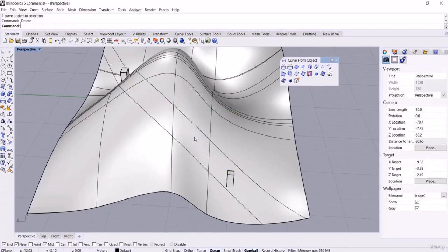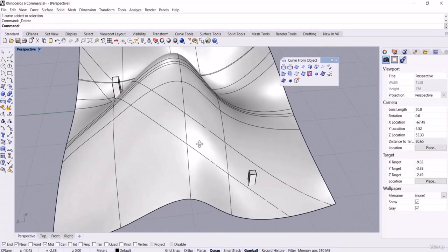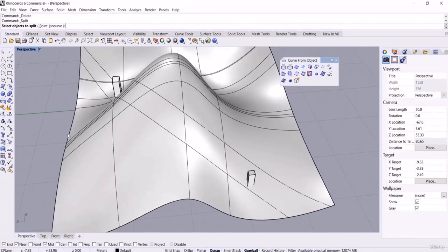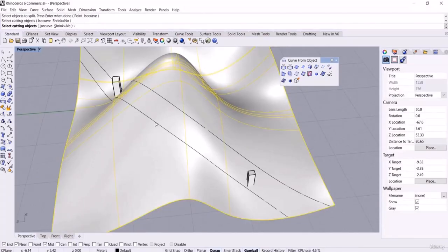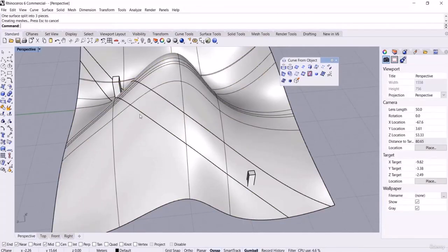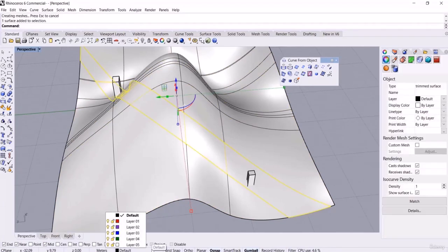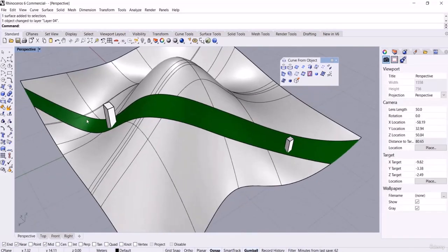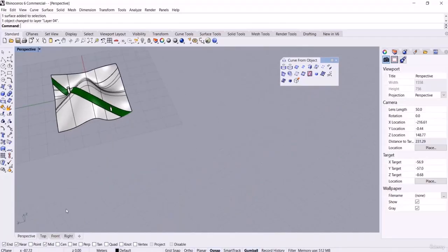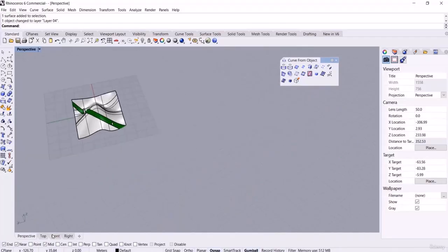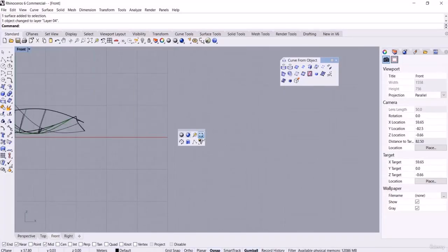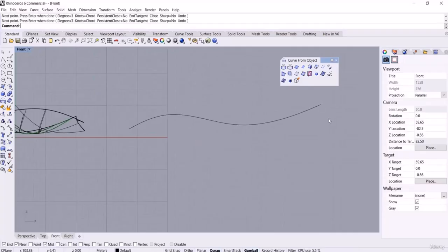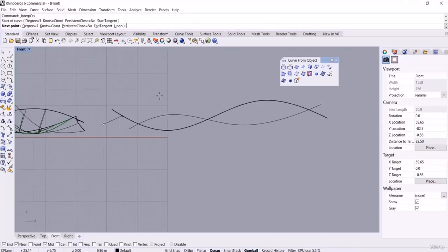And if I delete the middle curve, watch this. Here we got a road between these two objects. Then I can split these and assign them to a new layer this way, like a ribbon. Well done. And in order to have a review upon the offset curve on surface command, I'm going to give you